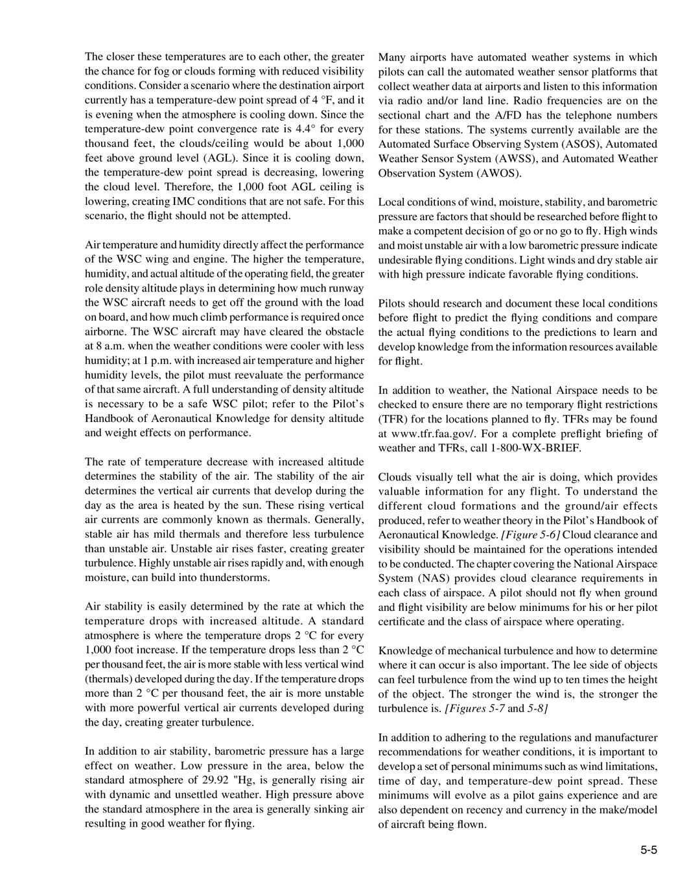Many airports have automated weather systems in which pilots can call the automated weather sensor platforms that collect weather data at airports and listen to this information via radio and/or landline. Radio frequencies are on the sectional chart, and the A/FD has the telephone numbers for these stations.